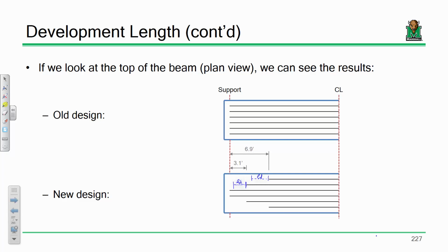And that's what we've done here. That's a great point. It very well might not, the development length very well might go out here. And then you're like, well then what do? Well, you just have more bars, which is why we end up just extending it a long way anyways. That's a good question. Does that make sense?